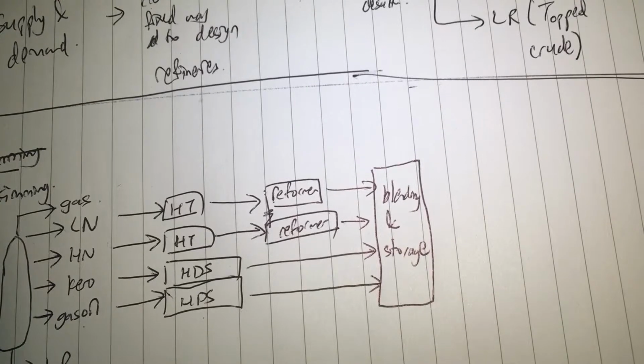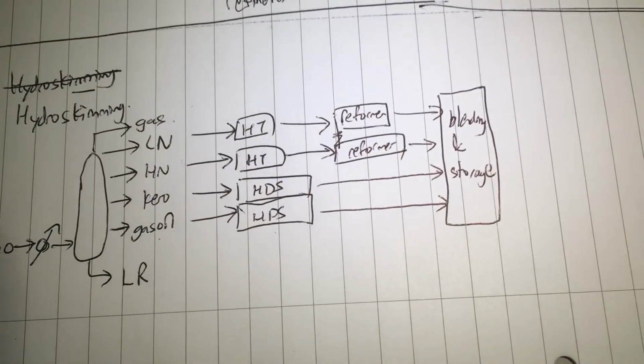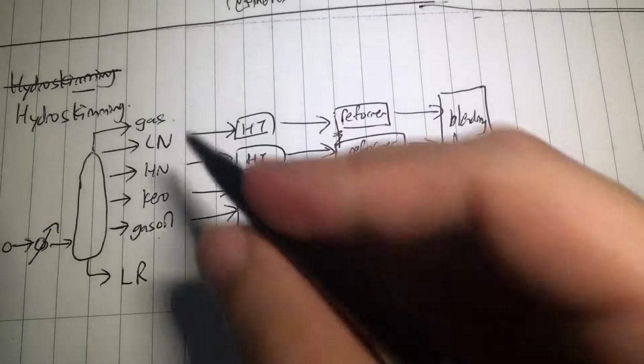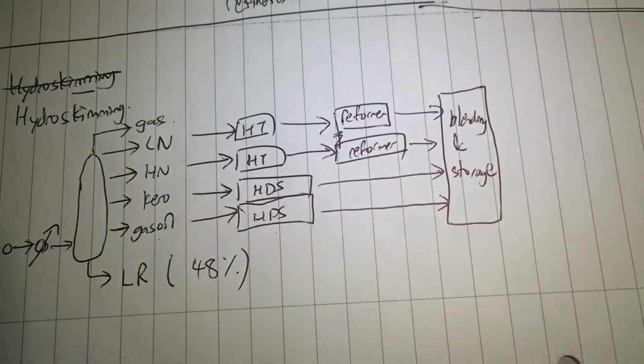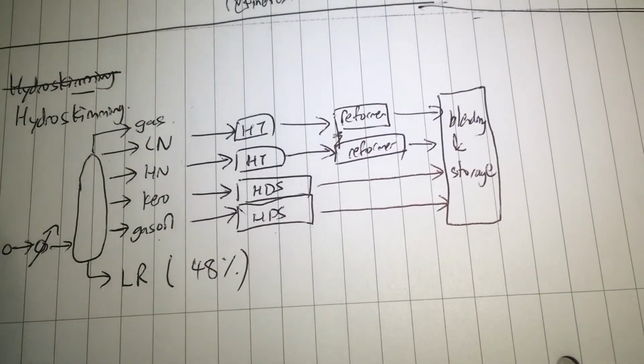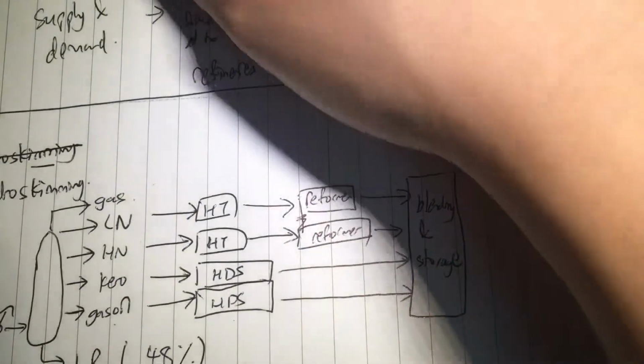But as you can imagine, remember that crudes nowadays have a lot of heavy products. Some can go as much as 48% over here. As you have seen in our crude oil assays from ExxonMobil, it's probably not so viable to have a hydroskimming refinery. So what they do is add the complexity just a little more. We'll have something called a conversion refinery or complex refinery.